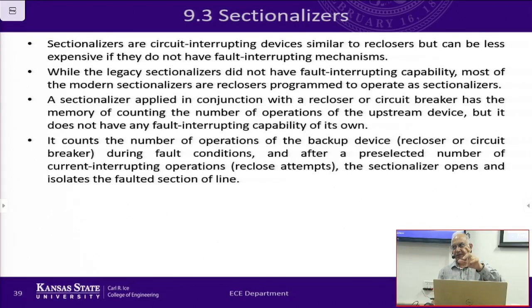A circuit breaker has a higher interrupting capacity compared to a recloser, because the recloser is deployed down the line and the fault currents are lower there. At the substation, the fault currents are higher. But sectionalizers may or may not have fault carrying capacity. Sometimes they don't have it, so it all depends.